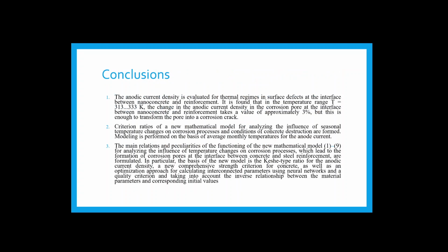And some conclusions here. The first one is that the change in the anodic current density in the corrosion pore or at the interface between nanoconcrete and reinforcement takes a value of approximately 3 percent, but it's enough to transform the pore into a corrosion crack.